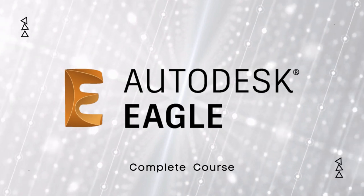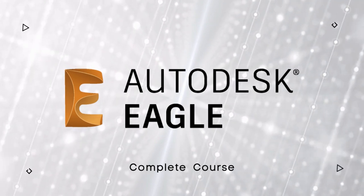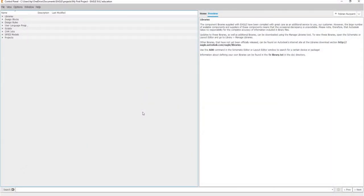After we learned about the overall Autodesk Eagle, maybe you notice what if we want to make a PCB design, but Eagle doesn't provide the library of our component. So, in this video, we're going to learn how to customize the symbol library for the Eagle schematic. We will learn both how to make our own library and how to import customized library from the internet.